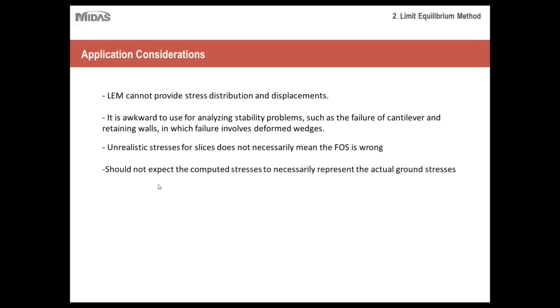Okay, so you should not expect the computed stresses to necessarily represent the actual ground stresses. Just to reiterate, actual ground stresses and computed stresses for your slices are two completely different things. So don't be discouraged, or don't worry if you seem to get stresses that seem to be kind of high or low. Just as long as your factor of safety is within reason, you should be all right.